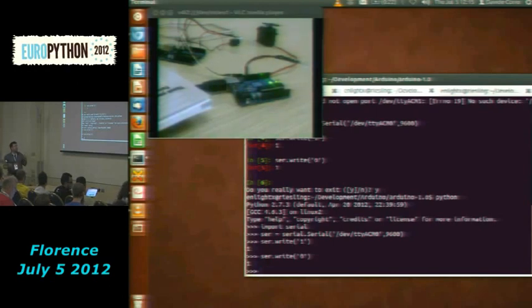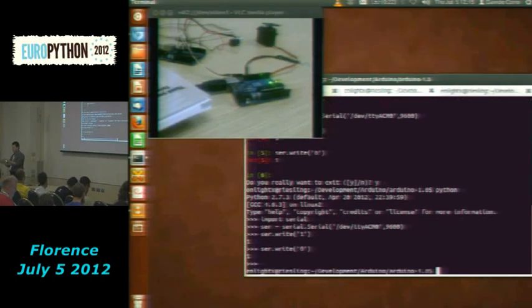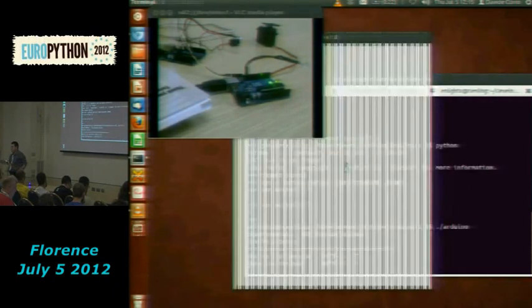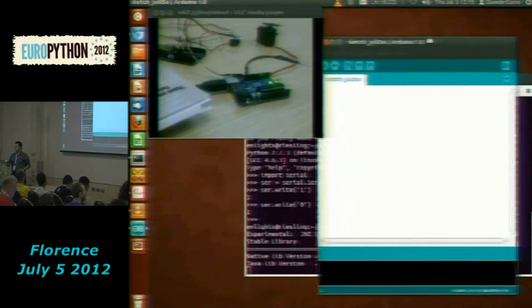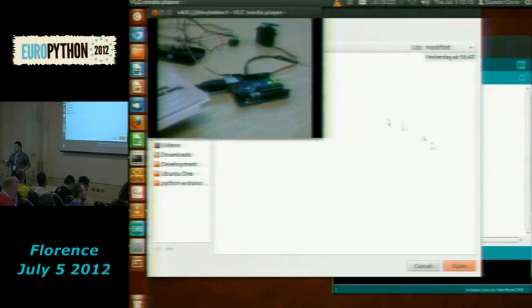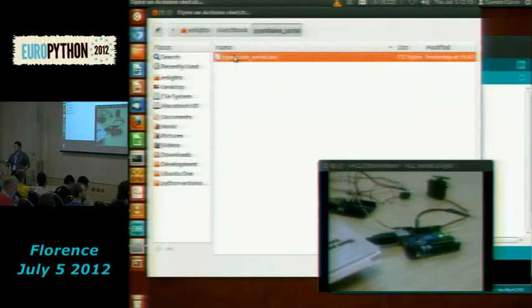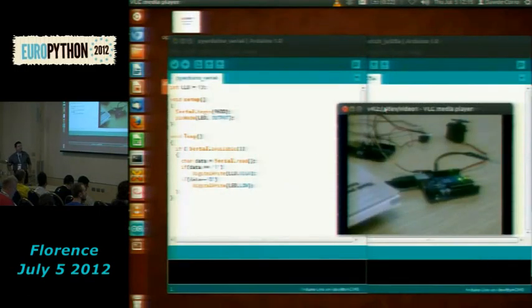As you can see, it's very easy to interact with Arduino this way, but we have to see what I put on Arduino, because we just sent a message, but inside Arduino I wrote a few lines of code that receive this text. I'm launching the Arduino IDE. I can load my sketch. Okay, here we are. As you can see, it's a sketch with very few lines of code. I listen for a 1 or for a 0, and in accordance to what I receive, I can put the LED high or low. Very simple.